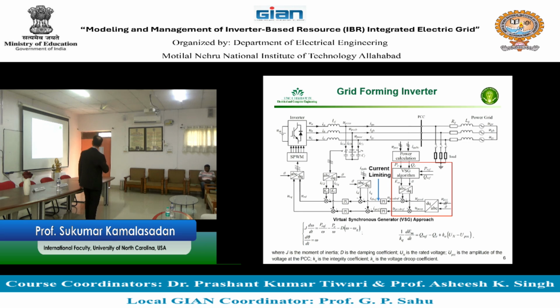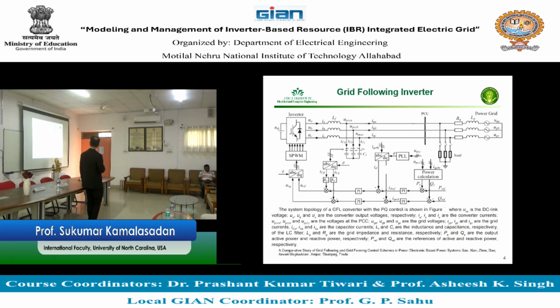And you are considering a voltage source combination. To control the inverter, we need the voltages and the currents connected to the point of common coupling. You control the inverter utilizing 3 different control loops. One control loop calculates the power and finds the difference in power, how much power I need to push to the electric grid.